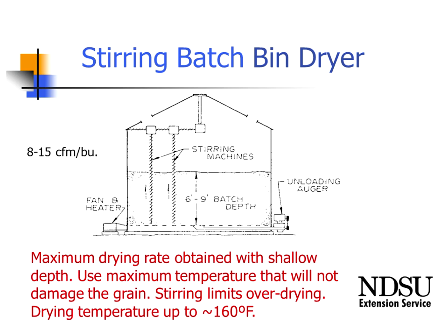The other thing with virtually all of our high temperature drying applications is we want to use the maximum temperature that we can that will not damage that corn. That's the way we're going to get the most energy efficient drying. And in this case, typically we're looking at drying temperatures maybe up to around 160 degrees Fahrenheit. But I always tell people, at least as a starting point, look to the company that you're buying the equipment from for their recommendation on what that drying air temperature should be.